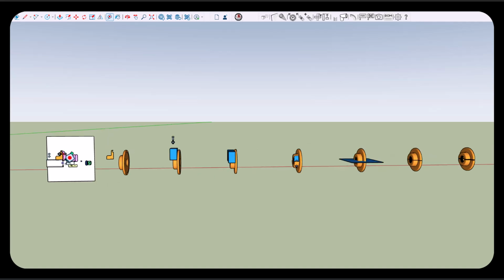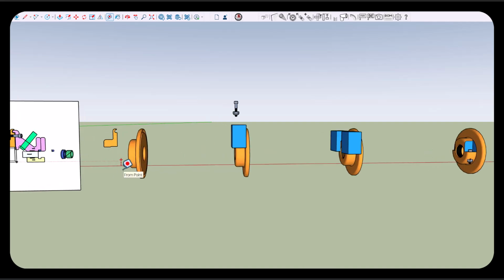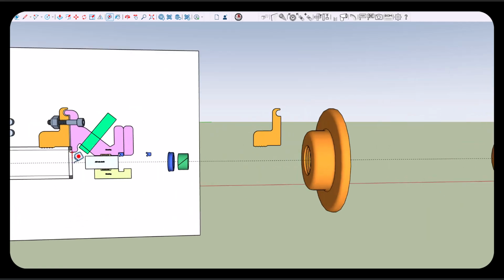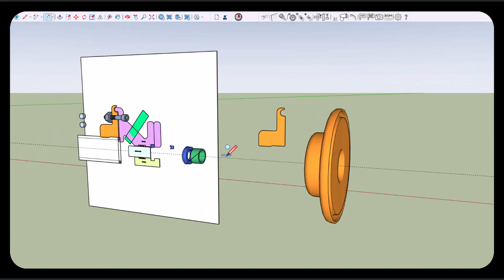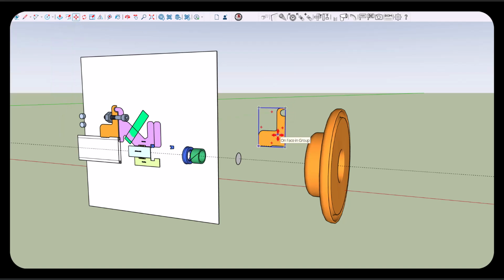And what I did with this clamp is in SketchUp, okay, SketchUp has a feature where you can make a circle. It's called Follow Me. So I can make a circle that's, so I'm going to put 2.5. So that's a circle that's a 1/2 inch in diameter. And I'm going to take this group and copy it, paste it in place, and so make it so it's not a group by exploding it.